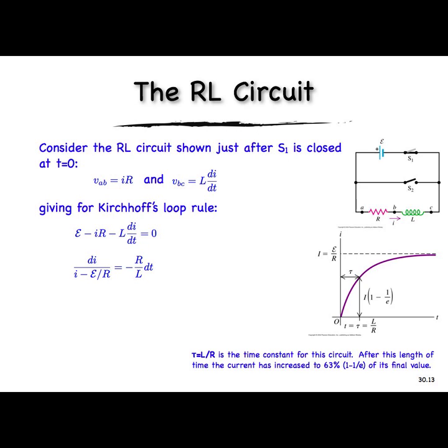And essentially what this is going to do is, when we have the circuit as shown, where this switch is closed and this switch is open, then the battery will drive current around the circuit this way. As it does, the current flows through this inductor. It starts to build up a magnetic field here. And then if we open this switch, that magnetic field is going to produce an EMF that's going to oppose that change and going to try to keep current flowing in the same direction.